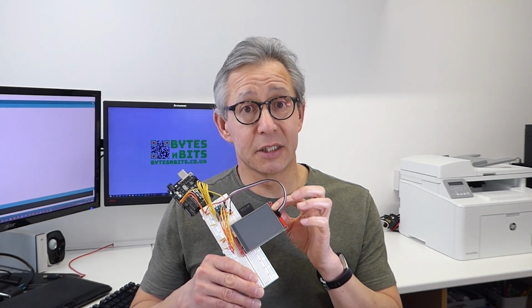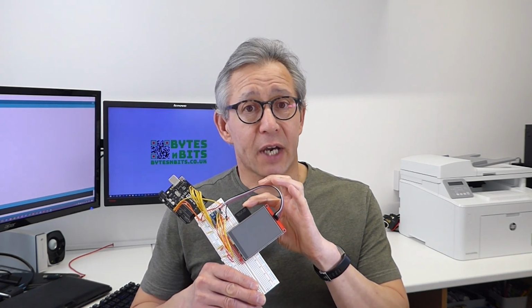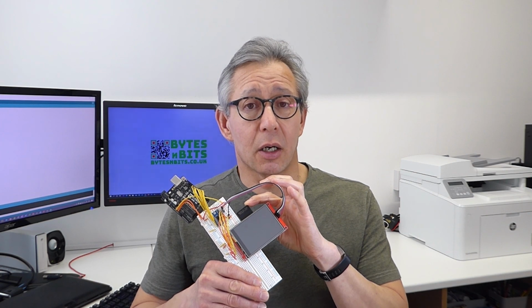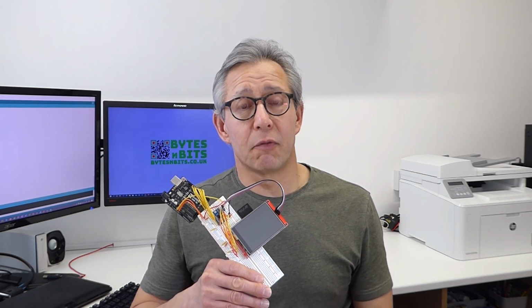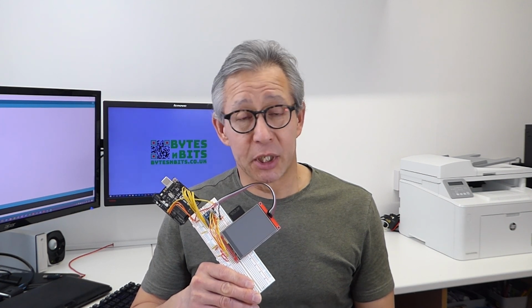So that's another project then using our Arduino, our LCD screen and our SD card. And we've seen then how any file that is on our SD card is just simply a collection of bytes of information, and we can then write some software to look at those bytes of information, decode them, and then in this particular instance then using a bitmap image, translate that data into actual pixels on our LCD screen.